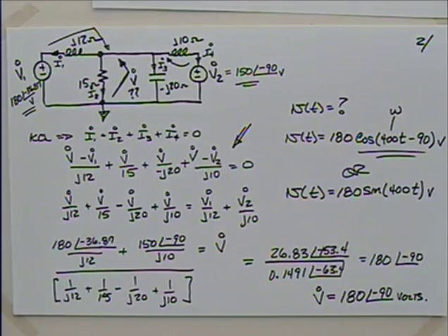Okay, so you could do it that way. So if you're looking at someone's solutions and it doesn't look like what you've got, check the trig operator. Maybe they've switched it on you. Questions of that? A real good solid problem, converting from the time domain to the phasor domain, doing the problem in node or mesh or whatever, and then finally converting the answer back to time domain.